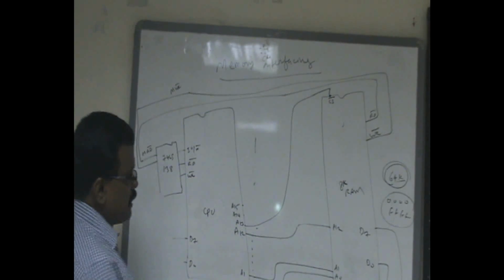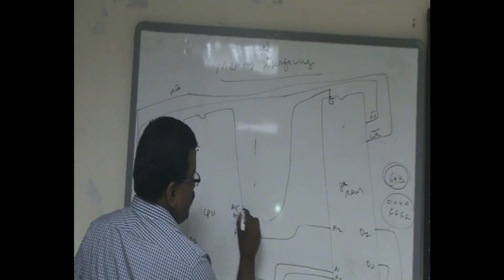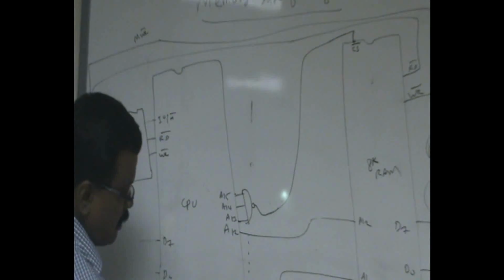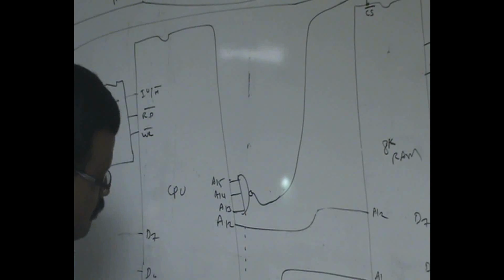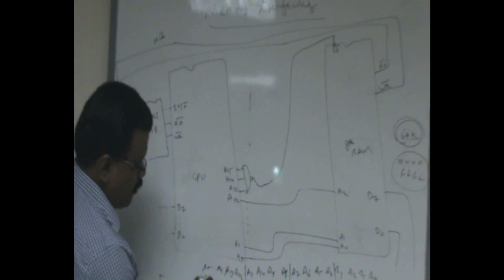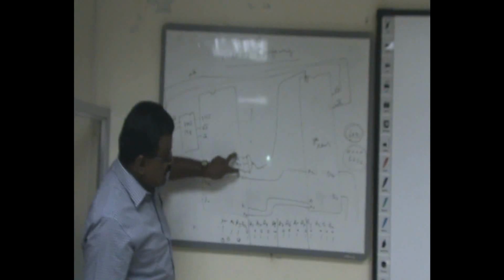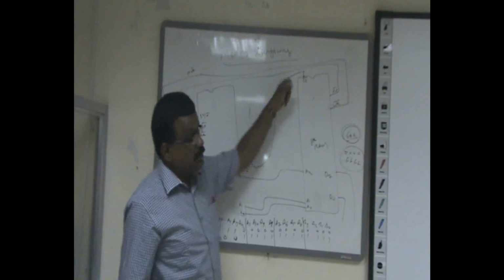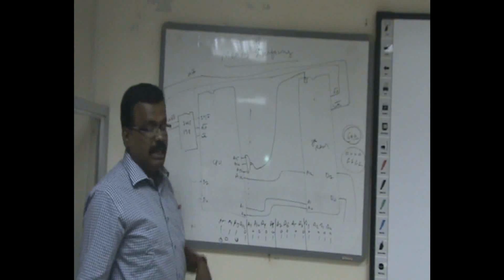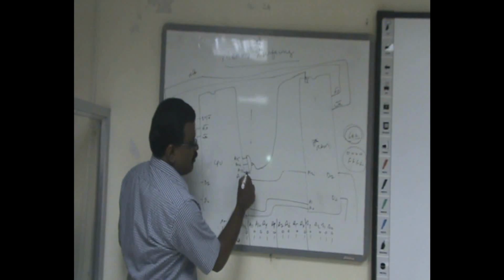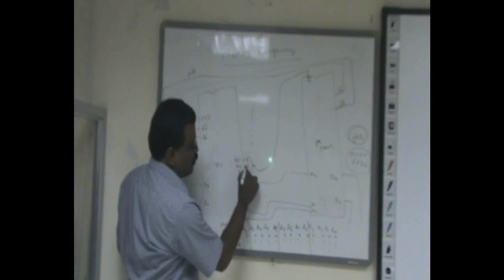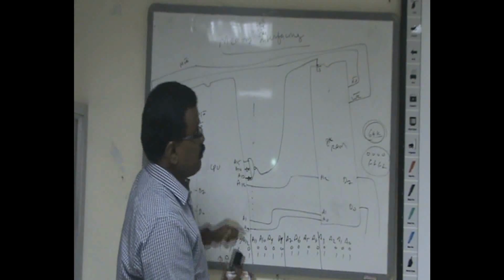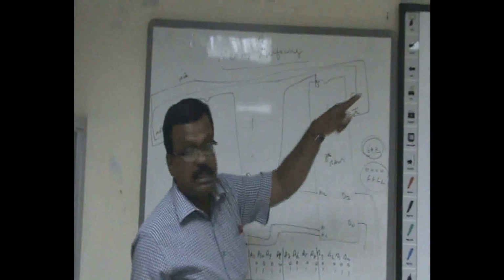Now in the case of a full decoding system, if you take the previous case, this is what we have drawn, where A13, A14 and A15 should be 1, 1, 1. Now by using these 3 address lines, 8 different chip select signals can be obtained, 2 to the power of 3. Because I can use one inverter here for one combination, and for another combination I can use 2 inverters. So at that time this must be 1, this must be 0, 0. So this kind of 8 different chip select signals can be obtained.